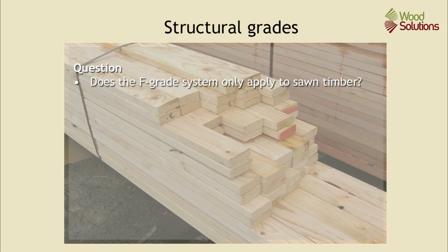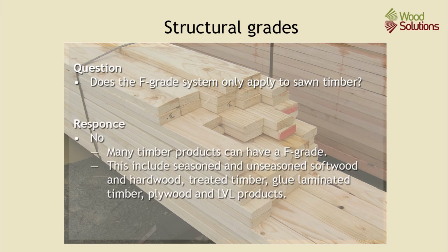Does the F grade system only apply to sawn timber? No, many commodity timber products can have an F grade. These include seasoned and unseasoned softwoods and hardwoods, treated timber, glue laminated timber, plywood and LVL products.